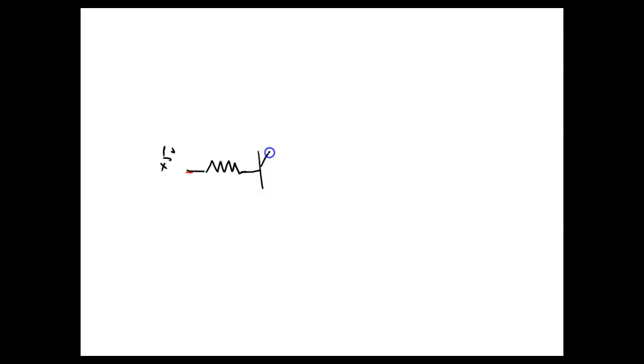And I'm going to bring this over here, and then we're going to come up here and put a light emitting diode. Then we're going to connect this to plus 12 volts. So the voltage levels don't have to be the same. They just have to have the same common.